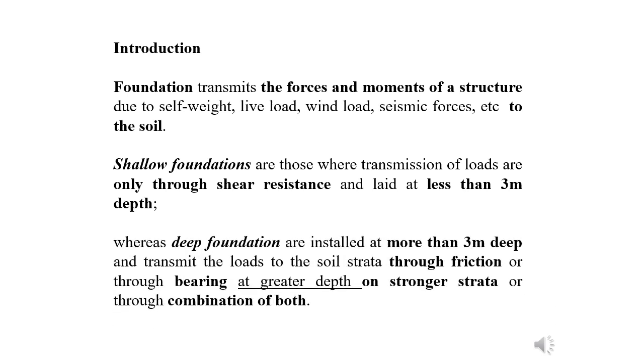The second thing, the deep foundation. Already we have talked about the pile foundation, friction piles, end bearing piles, right? How the load of the structure is going to be taken by the pile foundation. The pile takes the load due to the friction resistance working along the periphery of the piles, as well as the load carried by the end of the piles, bottom of the pile, and both are going to take the load of the structure.